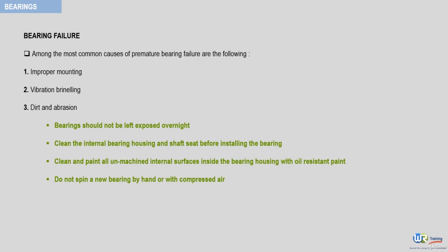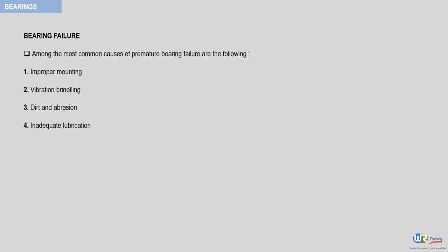The next common cause is inadequate lubrication. Inadequate means not enough lubricant, and it also means the wrong type of lubricant. If the lubrication is insufficient, the bearing suffers short life from too much friction, high heat, and metal-to-metal contact between rolling and stationary elements. For horizontal shafts, the proper oil level is halfway up the lowest ball or roller in the bearing assembly, as depicted in the following figure.